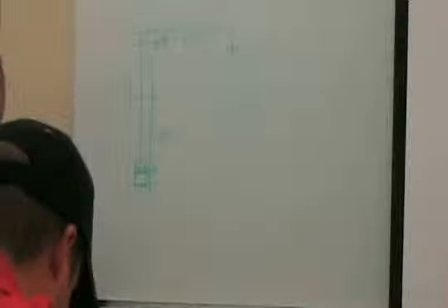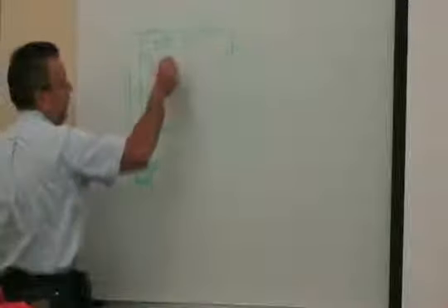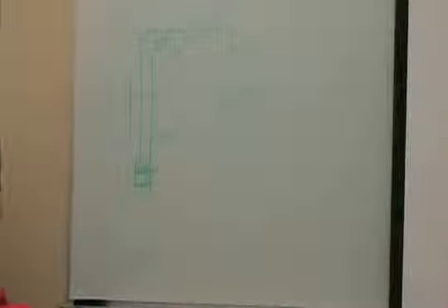So when your unit calls for heating or cooling, that energizes that pump? Actually, I have a pressure tank here with a pressure switch that maintains a certain pressure. So when your valve opens to your heat exchanger, the pressure drops, and the pressure switch starts the pump.